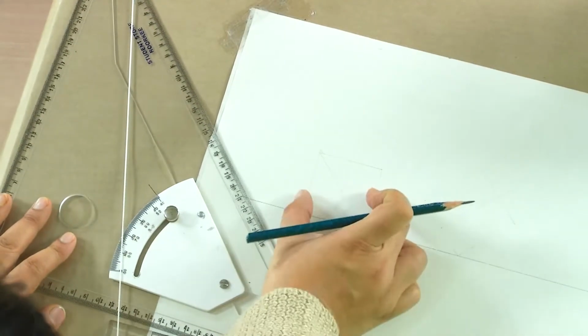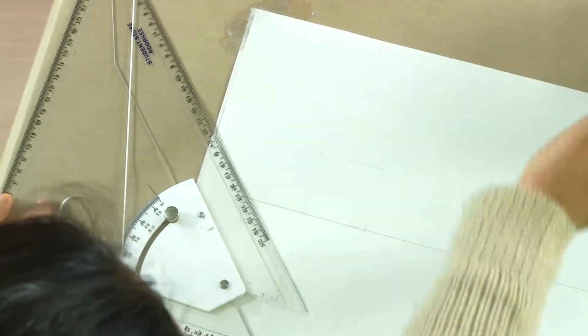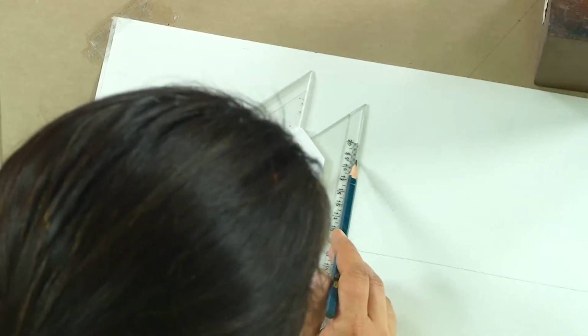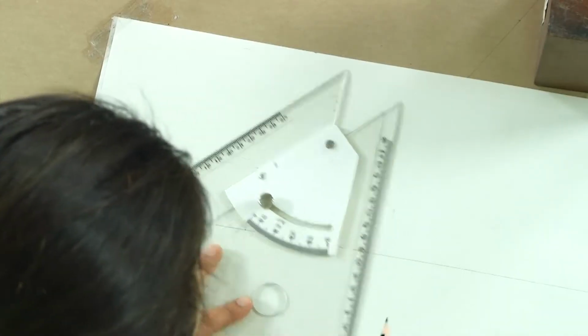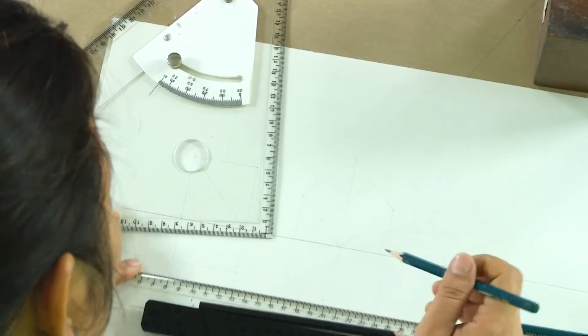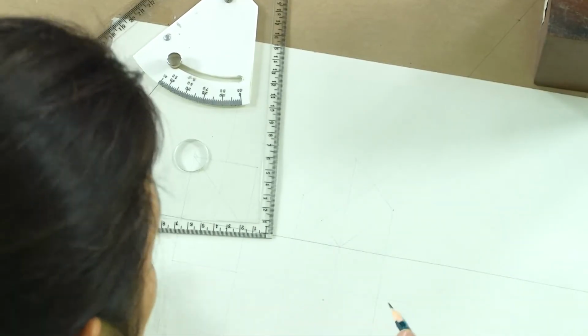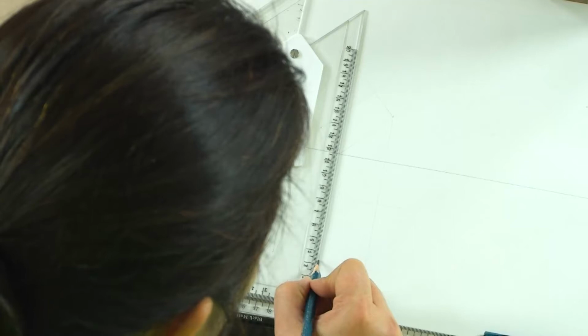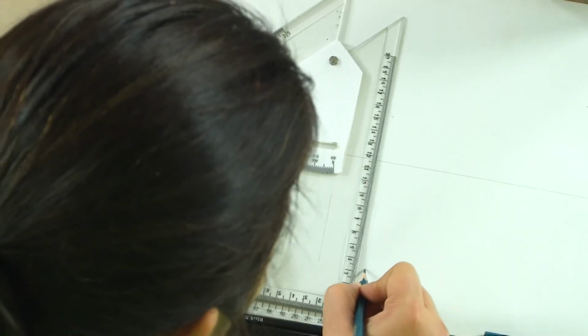This same square, the face which will be seen from the front, is now inclined at 45 degrees to HP, because this face was also parallel to the axis, and now when the axis is inclined at 45 degrees, this is what we see. Now, what happens in the top view? We see two of the faces being visible now.